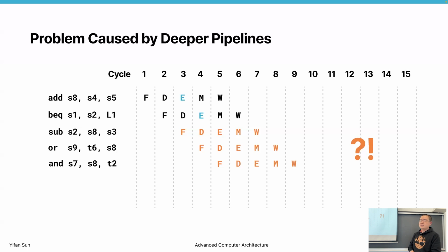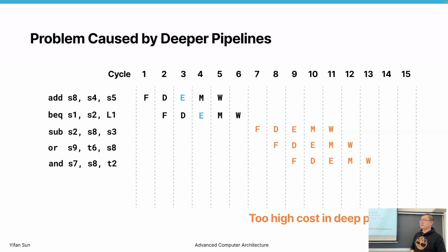So how can we solve this problem? The quick and easy way, the efficient core way, is to just move it back and wait until the result comes back. We probably don't need to wait until this point; we can start as early as cycle 4, right? So it inserts actual bubbles to account for this branch execution. In a 5-stage pipeline, it's probably not a big problem. It only adds 2-cycle, 3-cycle, or 4-cycle bubbles.